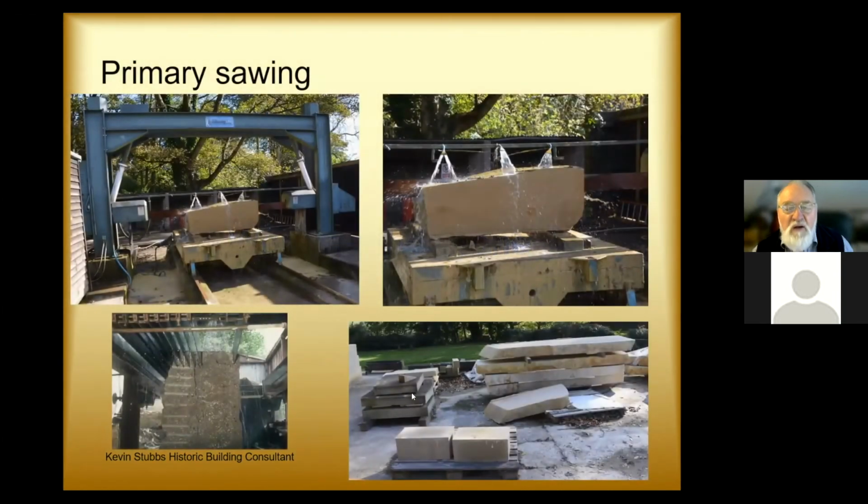Well, the working of the stone these days is done mechanically. That's useful then for turning into the ashlar stone that you need to use. If you want paving, this is a block of York stone. It's been cut on a huge frame saw, and you can see you've got multiple blades cutting down into the stone, the block of stone, to create your slabs.